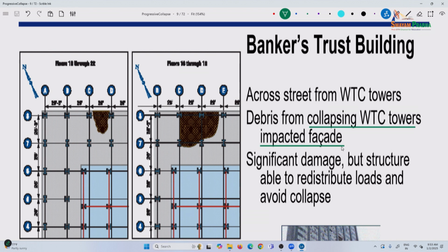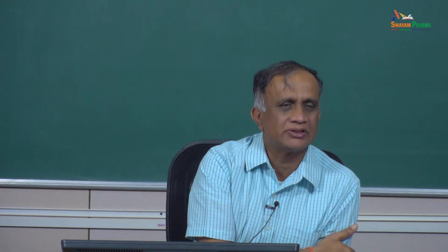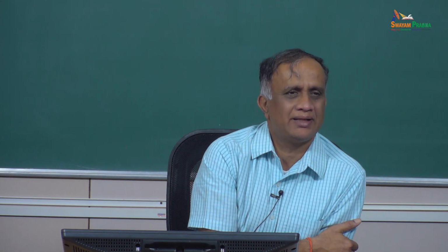In case of walls, for example, you will not have progressive collapse, but if you have adjacent buildings, maybe you could consider progressive collapse in such scenarios. Basically your question. That is an alternative design. If you do not consider protective design, you can just consider alternative design for progressive collapse, and that way at least the structures are protected.